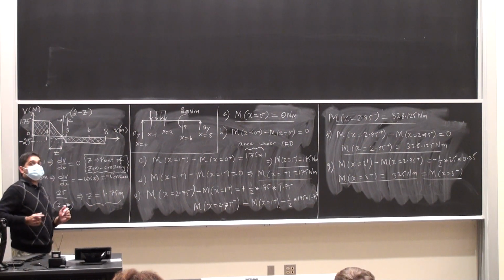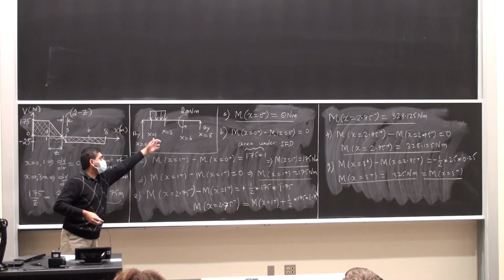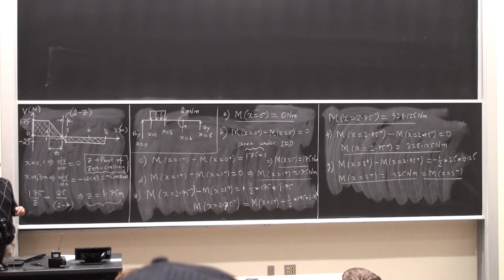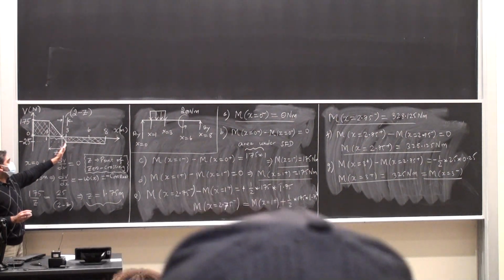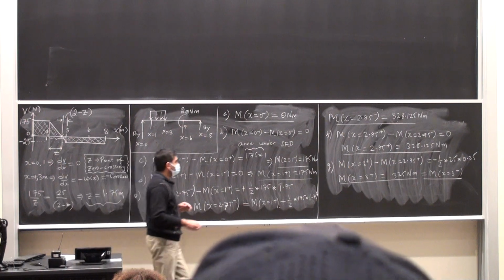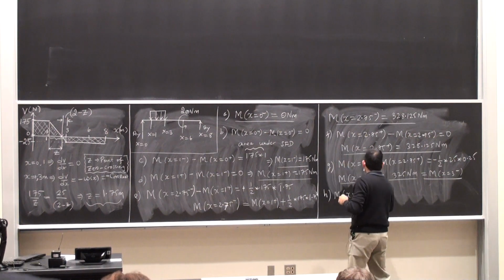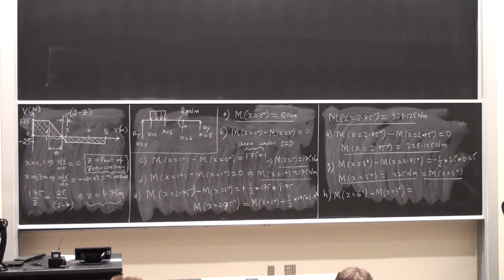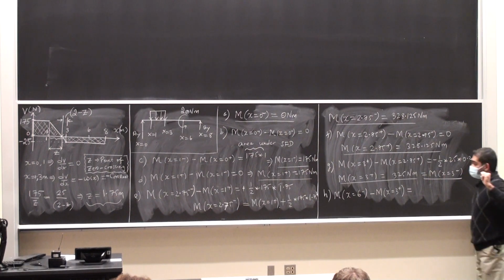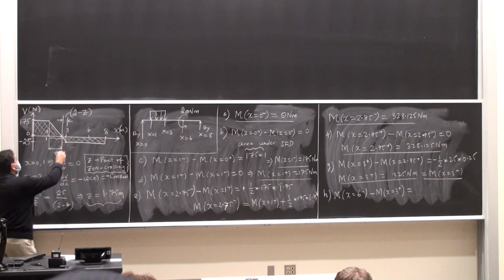Now we come to a special location on this beam where there is a couple moment acting. Which is why you need this guy in tandem with the shear force. Okay? So, I'm going to go from 3 plus all the way to 6 minus first. M at x is equal to 6 minus, M at x is equal to 3 plus. Can somebody help me unpack this guy? What's this going to be equal to? Area under the curve, which is -25. Beautiful. So this is going to be 3 times 25 with the negative side. This is the 3 meters.